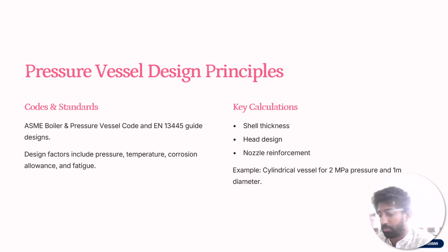We have to consider pressure, temperature, corrosion, and fatigue, because the pressure vessel is made up of some material, so there is a chance of fatigue. So you have to consider that. What calculations do we do? We do shell calculations. The shell is thick or thin, depending on what type of pressure vessel it is, a thick pressure vessel or a thin pressure vessel.